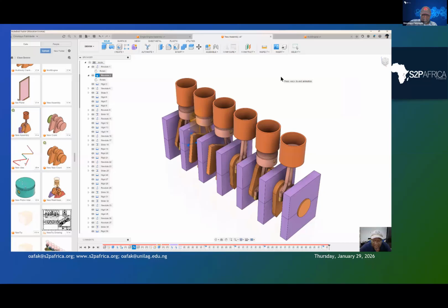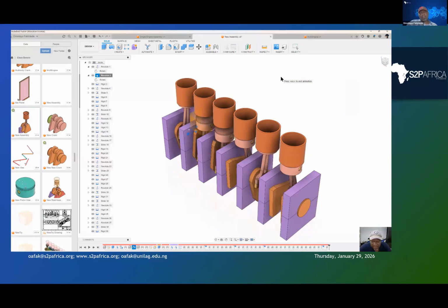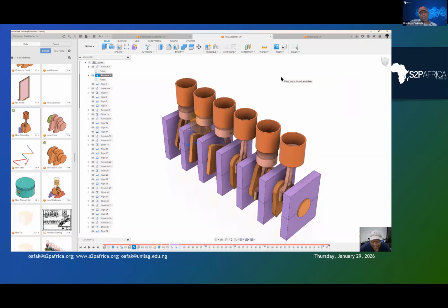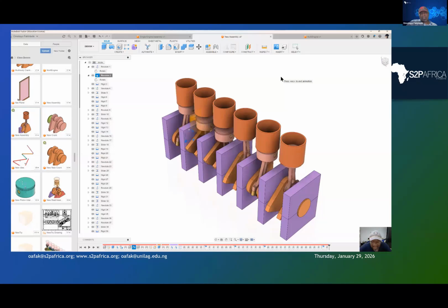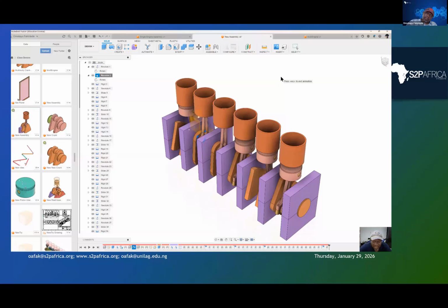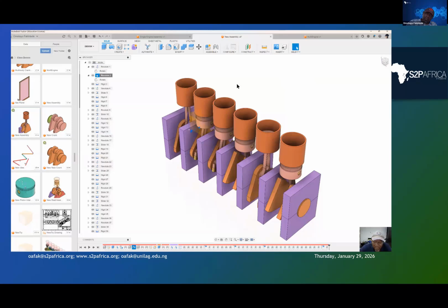The assembly of each cylinder is the same process. The only thing that distinguishes one cylinder from the other is the firing angle, which we computed in an earlier slide. So once the firing angle is correct, then you rotate statically to that firing angle before you do your final rigid connection between the parts. And you can see, if we stop this motion, one interesting thing is that it is the firing angle that dictates the way our crankshaft looks.